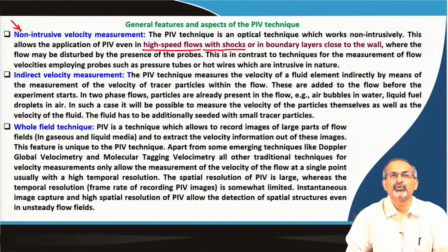Because if you want to put in a probe, if you want to put in a measurement instrumentation in any high speed flow, it acts as an obstruction to the flow. It would immediately produce shocks and it will disturb the flow altogether.